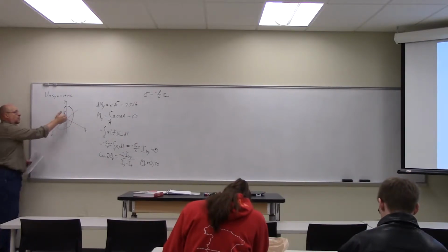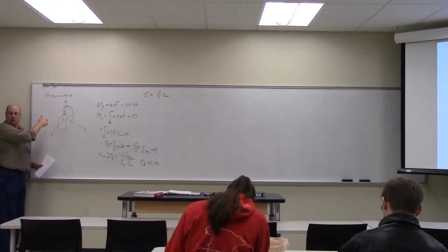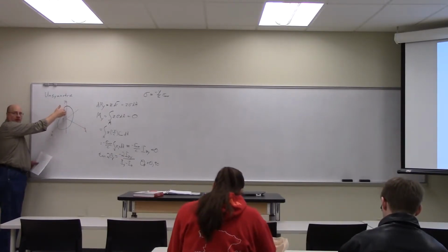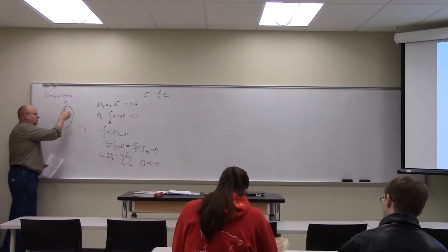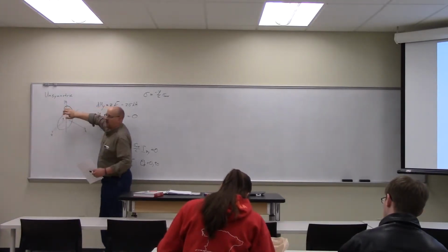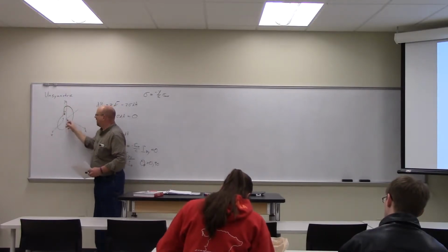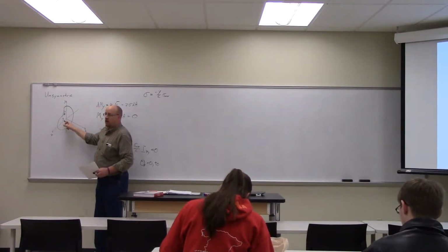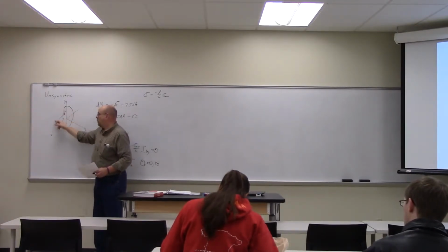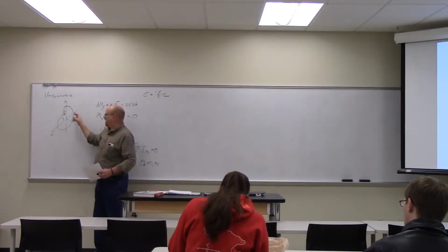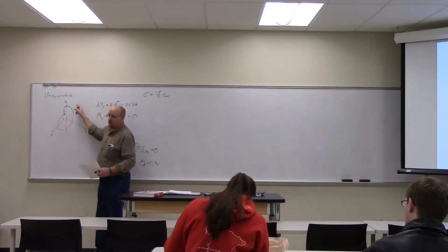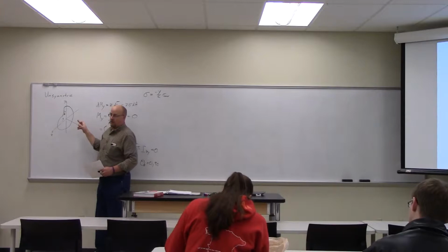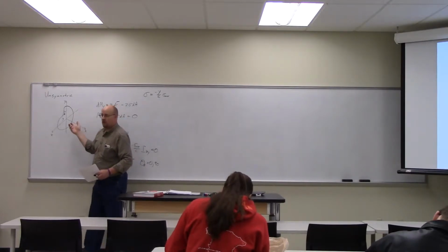Right, so we're bending it, we're getting compression here at the top. We've got just as much compression force acting on that side, which would cause the rotation one way, as we have force acting on the other side of the y-axis, so it's pushing down. So even though it's not symmetric, the total integration of the moment created by the force acting on this side is equal to the total integration of the moment acting on the other side. So that it doesn't try to twist.